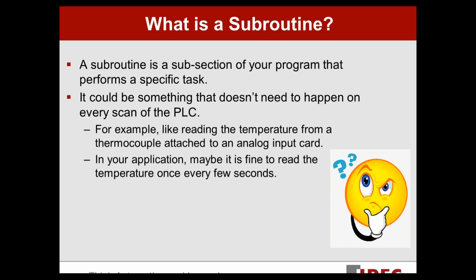For example, if you were around for the scaling and data conversion webinar that we did a couple of weeks ago, you'll remember that we read the temperature off of a thermocouple from one of the analog cartridges in the FC6A. Maybe that doesn't need to happen every scan of the PLC. Maybe once every 15, 20, 30 seconds, something like that, you want to read the temperature. That's an example of something that you could put into a subroutine.